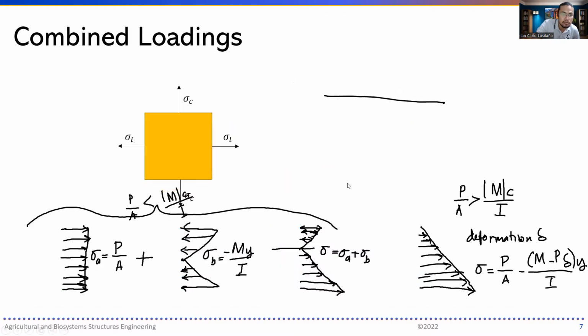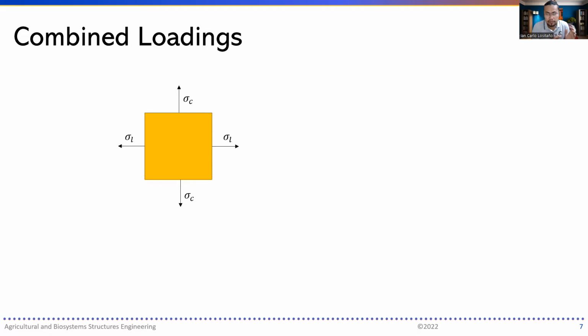Let us look into what happens, because we have to proceed to the transformation of stress, and this is very important in cases where there are failures inside a structure or a component. So let's look at the circumferential and longitudinal stresses that happen in an infinitesimally small portion of the pressure vessel that we were talking about a while ago. But if we introduce a shear stress in this kind of diagram, for example, it's like this. Now, if we do have a shear stress over here, then we are proceeding towards what the discussion is progressing into. It's the transformation of stresses.